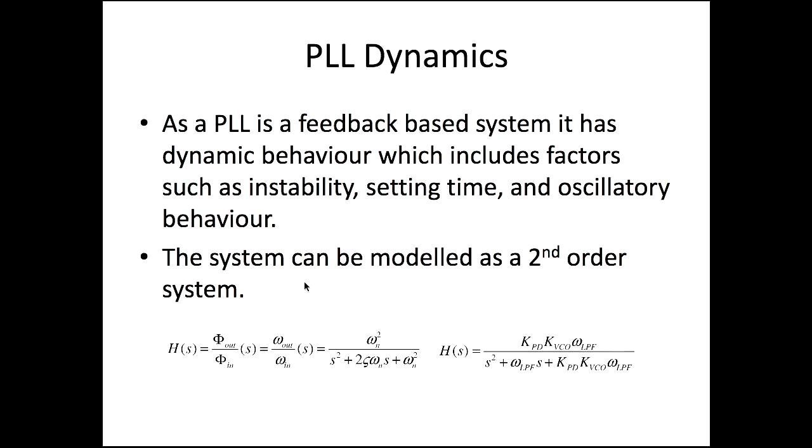One of the questions people might ask is, okay, can I connect any frequency to the PLL and the PLL will lock into it? No, it is not possible. That is only an ideal PLL. Based on the settings, they will say this PLL's center frequency equals 1 kilohertz, and you can synchronize maybe 1 kilohertz plus or minus some value. You can't have an infinite range.